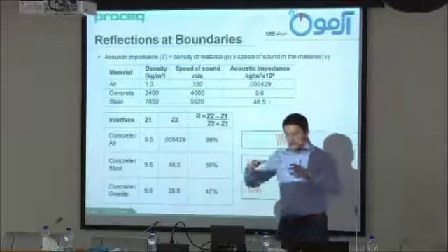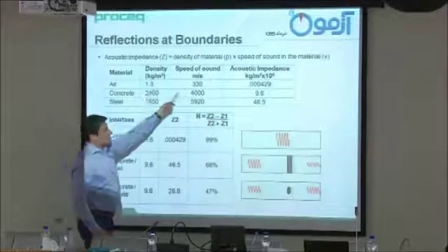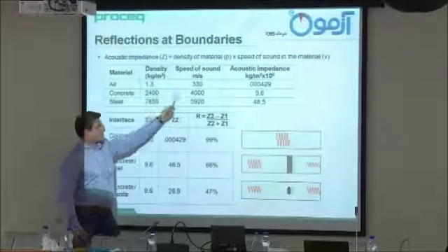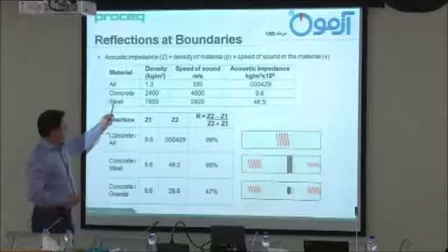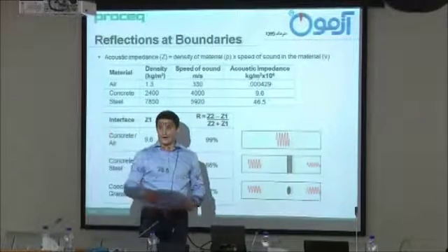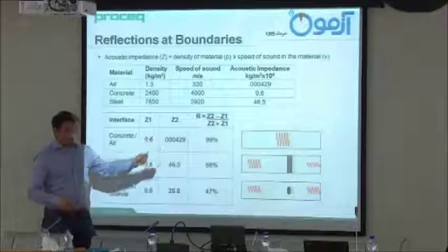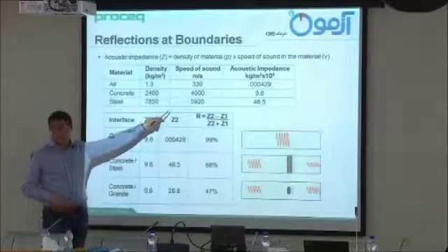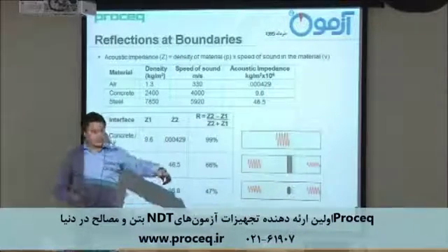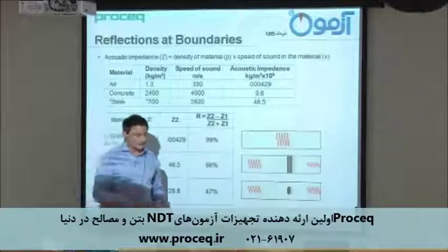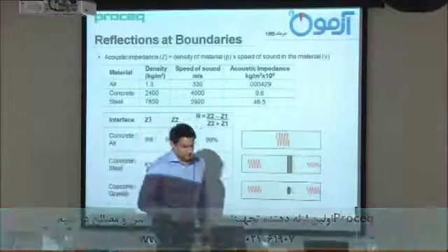So when we talk about homogeneity, it's also good to know the speed. Air has a slow speed. Concrete has 4,000. We have seen first 3,000 to 5,000. And steel is usually above 5,000 to 6,000, depending on which material it is. But when we talk about rebar steel, usually somewhere around 6,000. So this is good to remember all the time when you do a lot of projects with ultrasonic, because this will also give you the information: am I right or am I not correct?